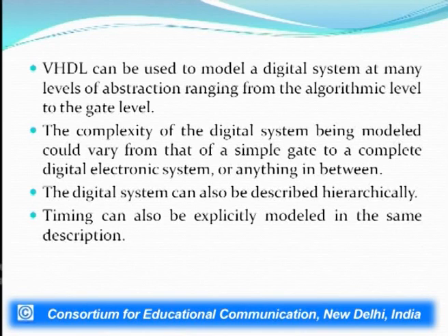Now, a digital system can also be described hierarchically. I can begin with a bottom-up approach or a top-down approach. Bottom-up approach refers to gate definition, followed by the definition of the circuit, and ultimately followed by the design of the entire system. Or a top-down approach is also possible, whereby the entire system is first defined, then the subparts of the system, that is the circuits, followed by the gates that are to be utilized by the systems. So the hierarchy is fully supported, be it top down or bottom up.